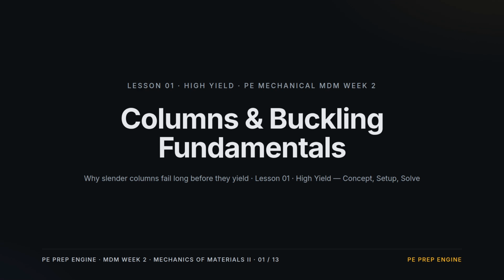Week 2, Lesson 1, Columns and Buckling. Machine design so far asked whether a part is strong enough. A column asks a different question. Is it stable? A long, slender column can fold sideways while the stress is still nowhere near yield. Today we build the language of that failure.